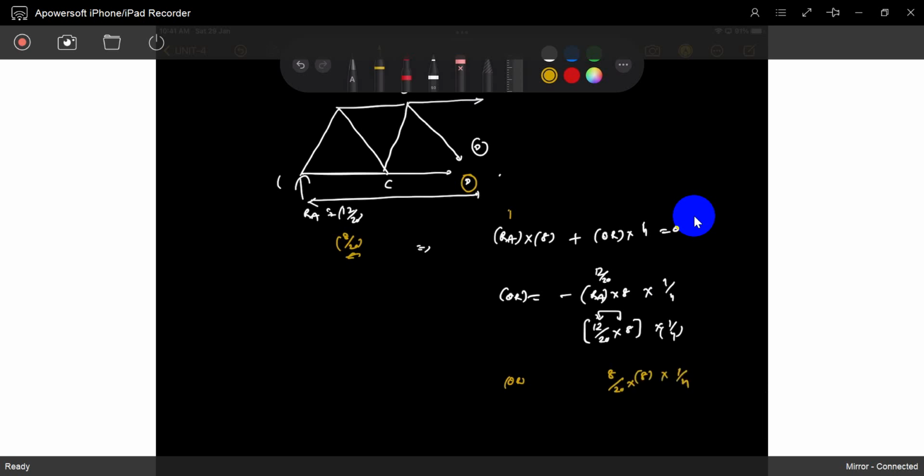1 by H. So now the next, E, is next F. F I choose, you will get 4 by 20 into 8. These values are reducing. Maximum only at D location only. The load is at D location only, you will get the maximum. Because we choose the moment with respect to the joint D. Understood? These values are going to be reduced. Again, it will reach the maximum when the load is at D. Remaining values are reducing. So it's the same, representing the influence line for the bending moment at the joint D.